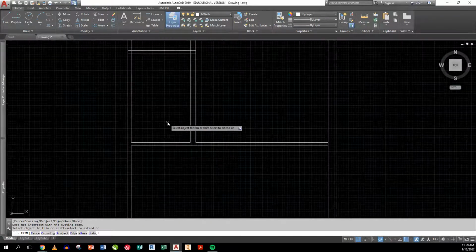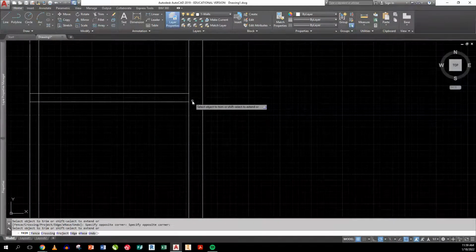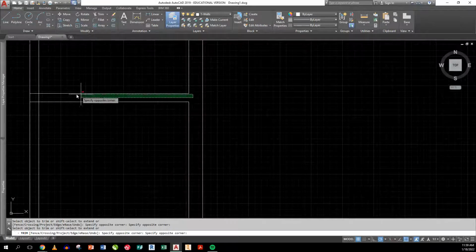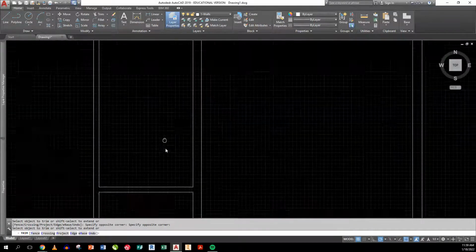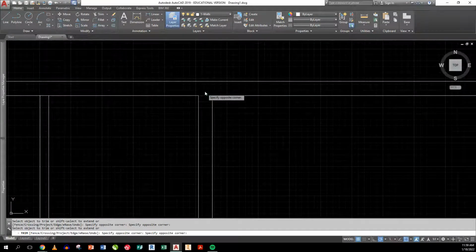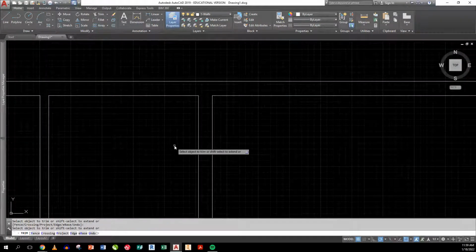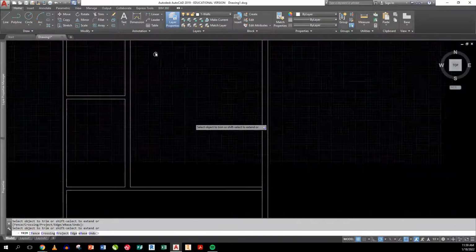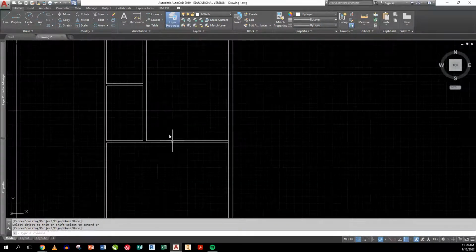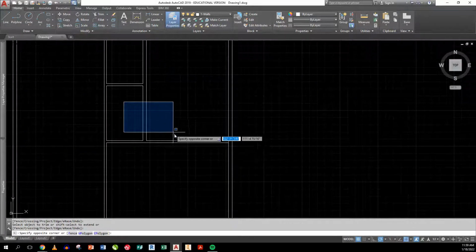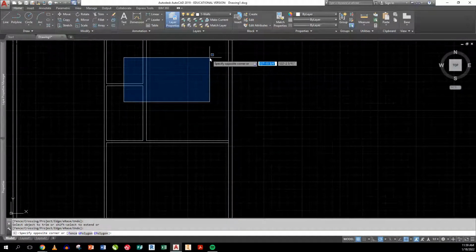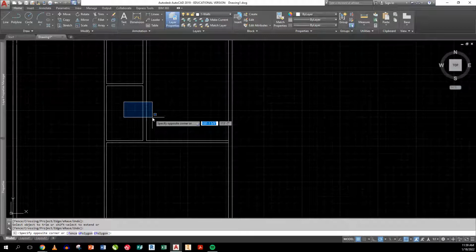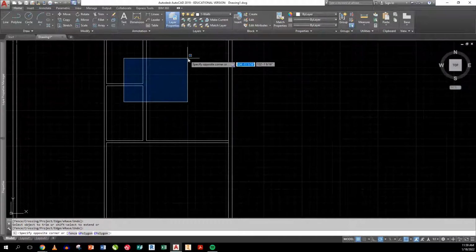It just touches it. If I go back up here to the middle, I can continue this process literally through this by using the crossing option there or the crossing option here. Go up here to the far corner, again, crossing option, or just pick on it. Either way works. Now, we haven't talked about those, but we're going to right now. You've got two options for selection tool. You've got the window option. See, it's blue, and it happens anytime I click and drag. So I click, I let off my mouse, so it's a quick click, and then I drag out to my right, up or down, doesn't matter.